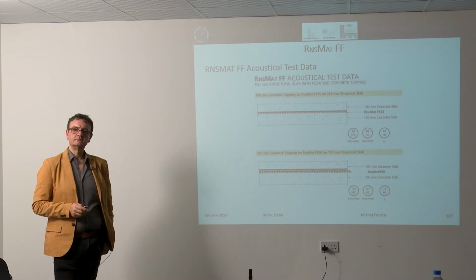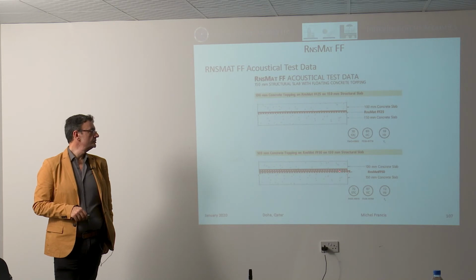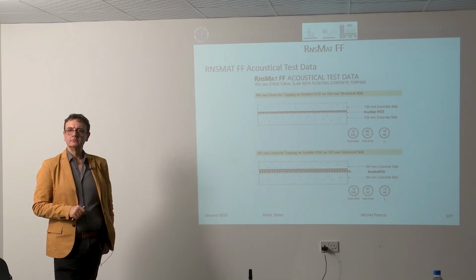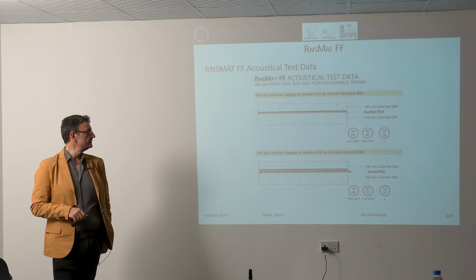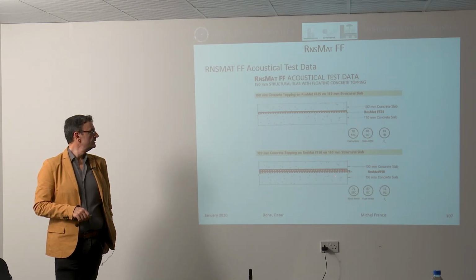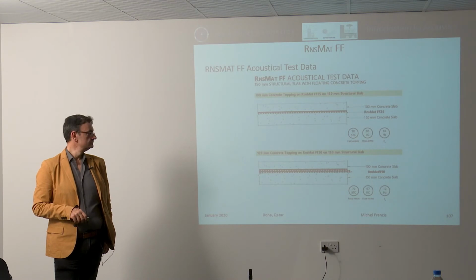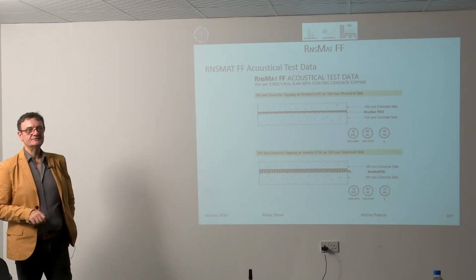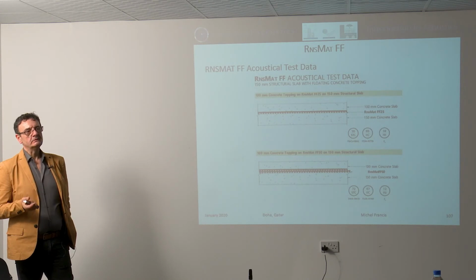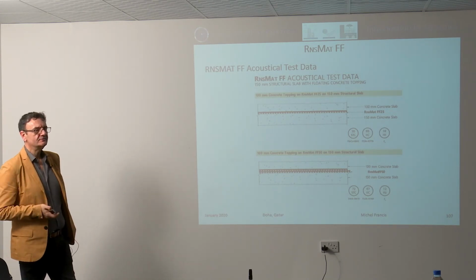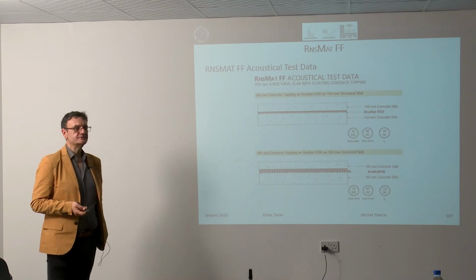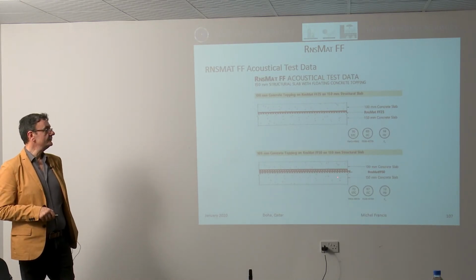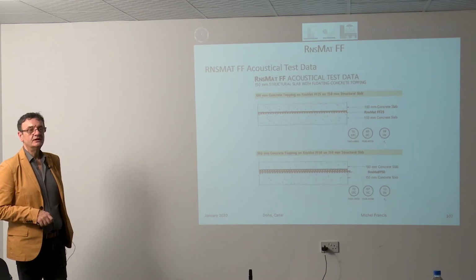When we apply 2 layers, do those grooves have to be symmetrical, or does it have to be arranged in a pattern? No, you just put them above each other. So this is 2 layers here. And adding each layer, the STC difference is 2. You can see here there is a 2 dB difference, which in my opinion doesn't add up to much. Best to go for this. But this I think is better for vibration, not only for noise insulation.